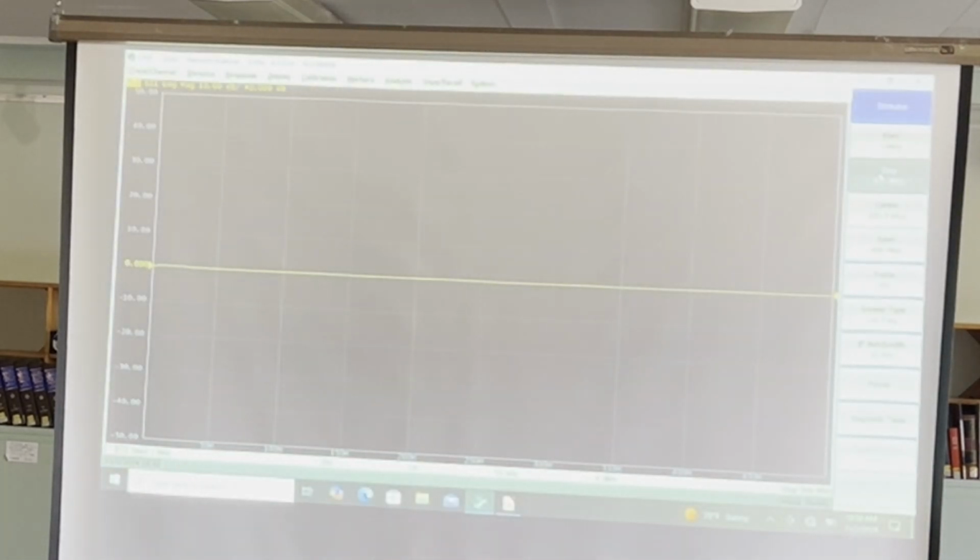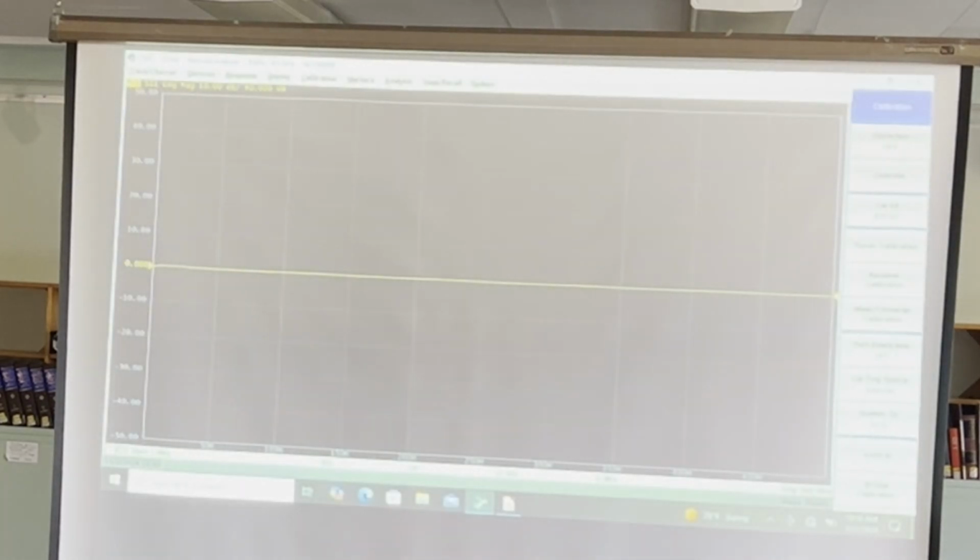The reason we want to do that is because it's going to calibrate within those two, so we're going to do a 499 megahertz bandwidth span here. Okay, and once we get that done, the measurement we'll come back to. We want to perform the calibration. Corrections turned off; actually, we want to turn that on.